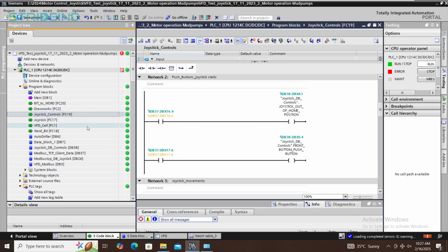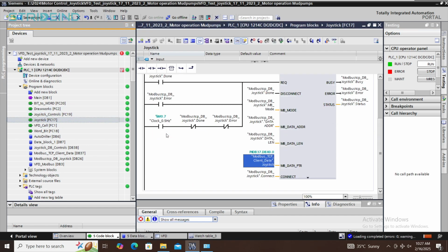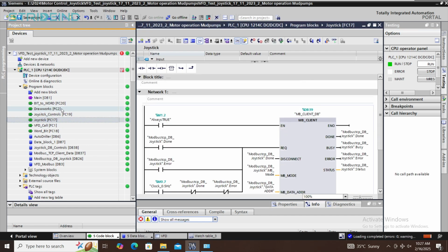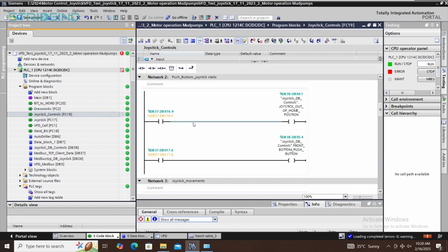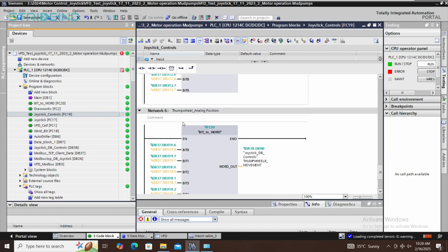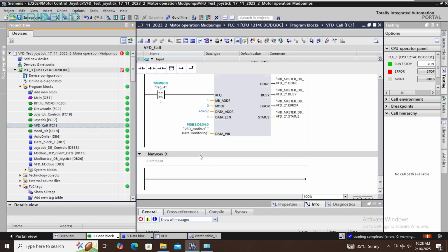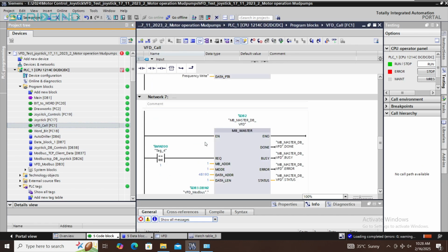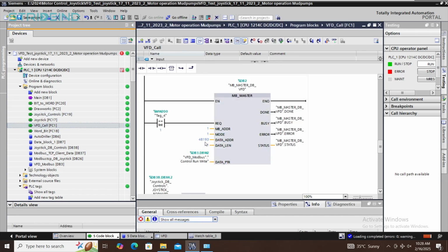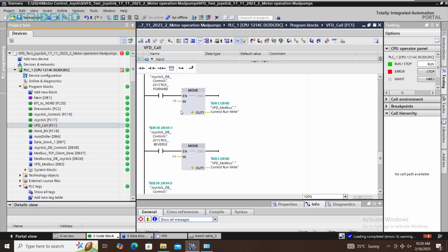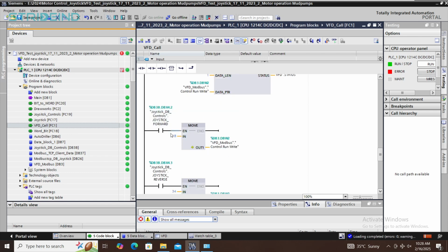Now we need to write. Now the frequency signal is to VFD, but we need to write the command or enable the command for forward direction. Before we had in the program for forward direction, but that is with the joystick. Now we will take that value, so we use this joystick forward parameter to VFD.